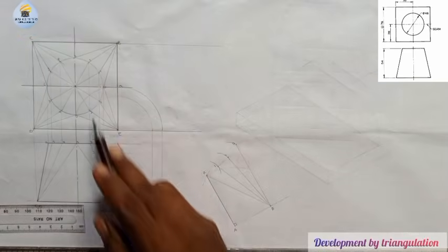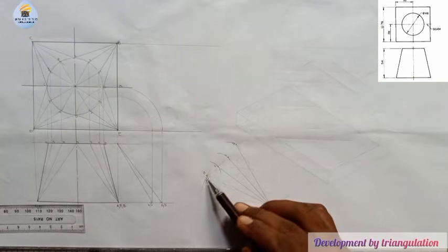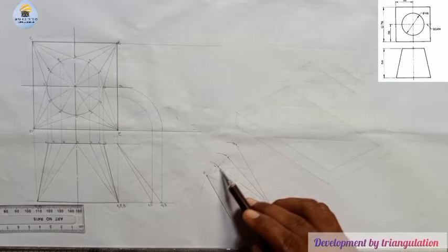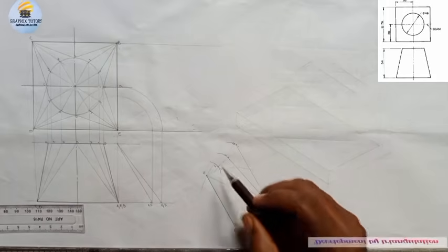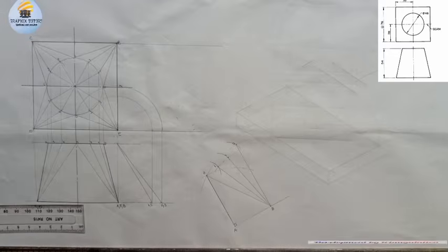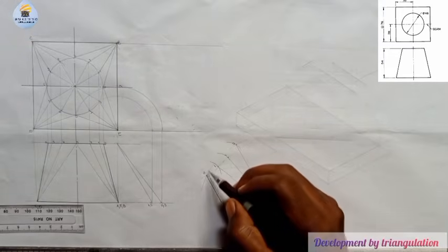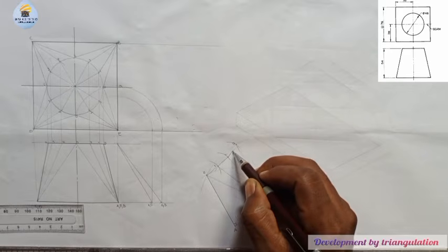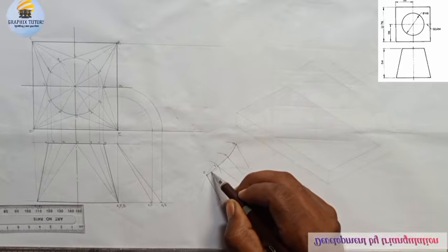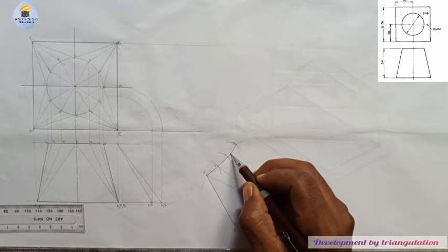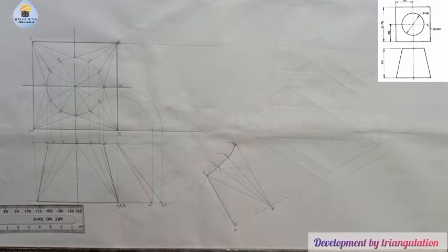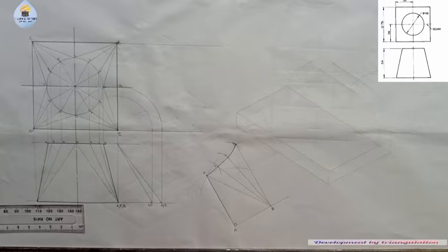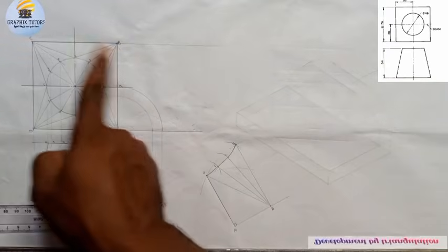This is what we did here. These are the true lengths here. So I'm using my French curve, and I'm going to join all this arc here. So I'll just join the arc. Or better still, I can easily use my hand here to connect the 3 dots together. You can see that? Connect the 3 dots together. Now I want to proceed again. We're done with that angle, so go to the next one.